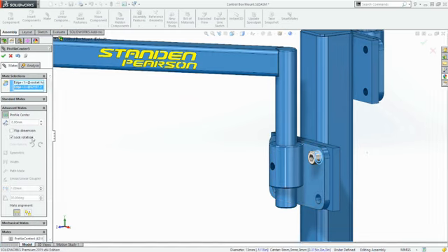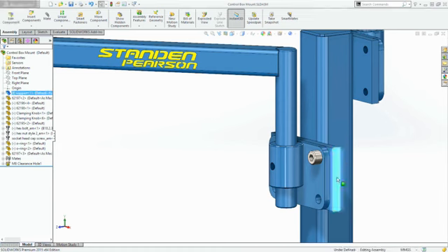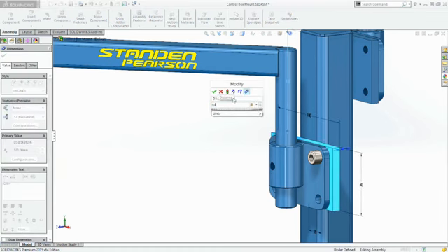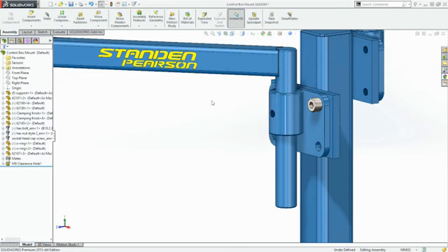Two circular profiles are locked to each other and the rotation can be locked as well, resulting in just one mate to fully locate a screw. If the size or location of the selection is changed, the profile centermate maintains the intelligence to keep them centered.